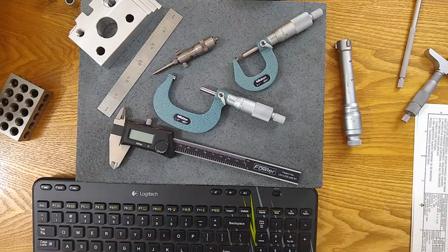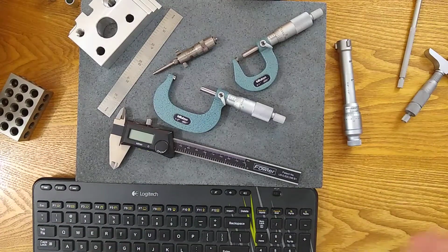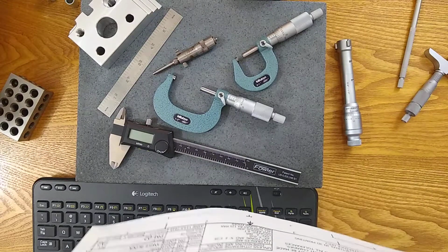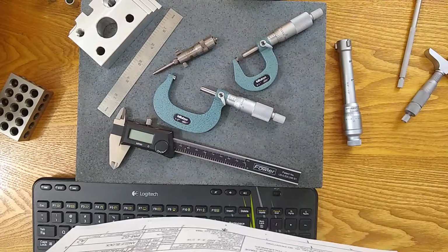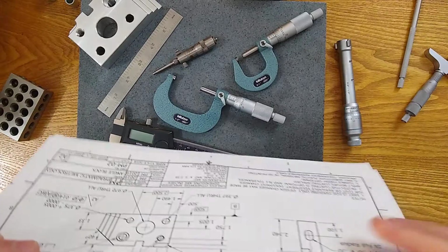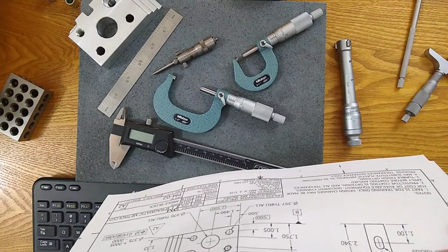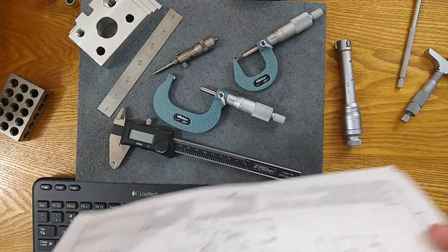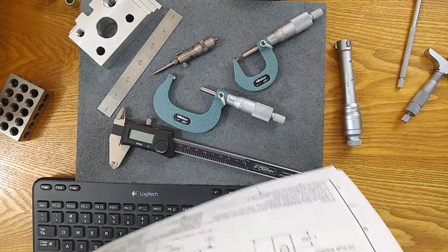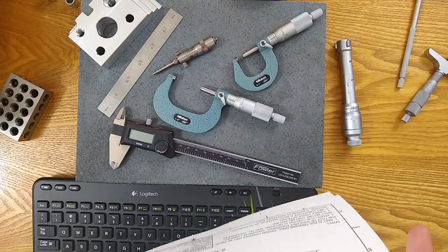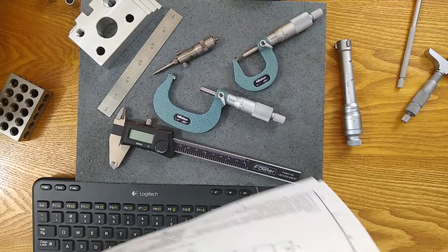Tolerance zone, gauge accuracy. If the tolerance zone is open, it generally leads to less expensive manufacturing, which leads to less expensive inspection. And when it's tight, the smaller the tolerance zone, the more expensive the feature, more expensive manufacturing methods, the more expensive inspections. Same thing with gauge accuracies.